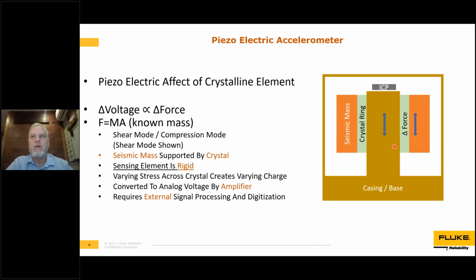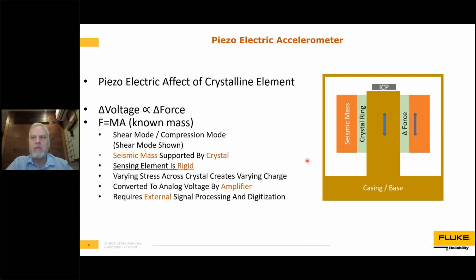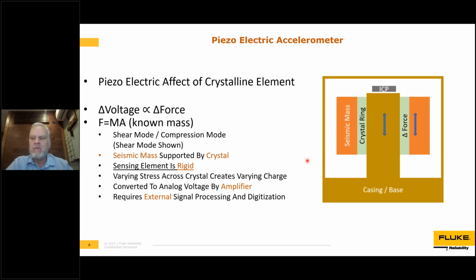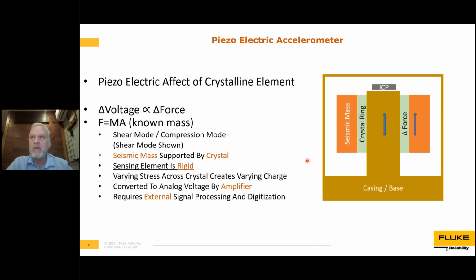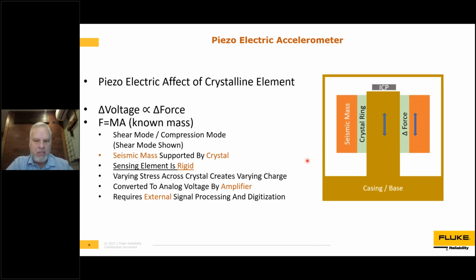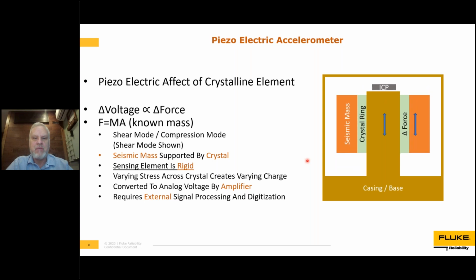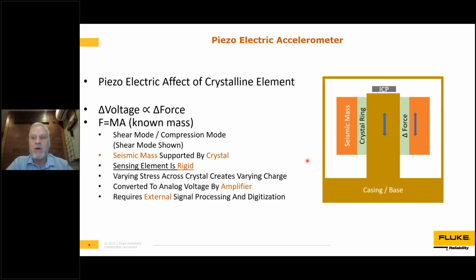One of the things I want to point out, if you can see the illustration, is that the whole unit moves as a single unit, and there are no internal moving parts. Very rugged, very long-lasting, with lots of advantages and typically very high dynamic range. There can be some fragility in these at super high Gs. You can destroy the electronics. You can damage these if you drop an accelerometer, for example. They can be very expensive. I know that our Triax accelerometer is well over $1,000, so you tend to not want to drop these, but they are very robust in general terms.